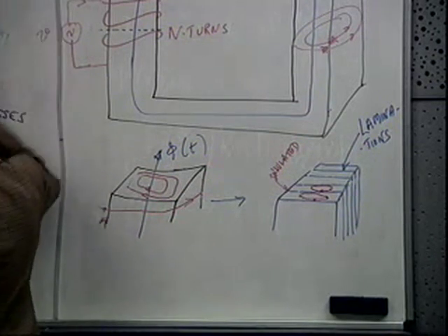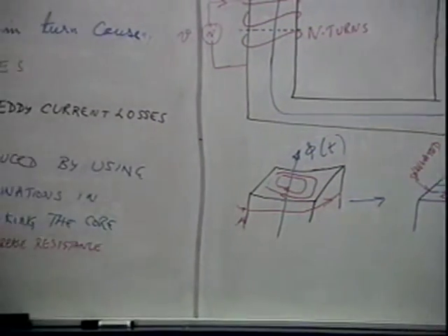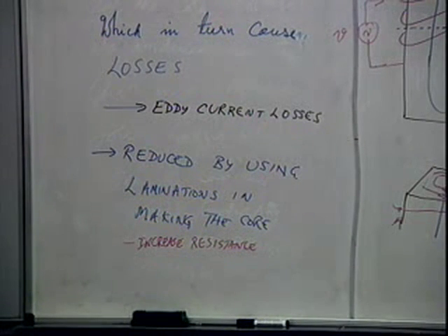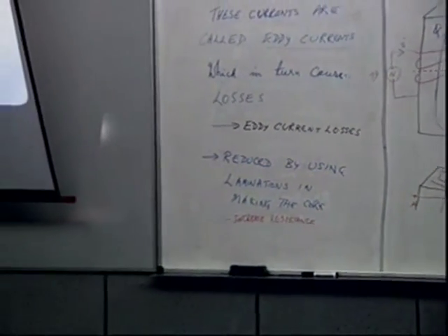If you do this, it reduces the core action. So doesn't lamination reduce the core action, the linkage? Lamination to some extent, yes, it reduces the flux path also. But that is small, because you stack it together; magnetically you don't want to change much, electrically you want to have a considerable increase. You are insulating the sheets. Several sheets are being insulated.